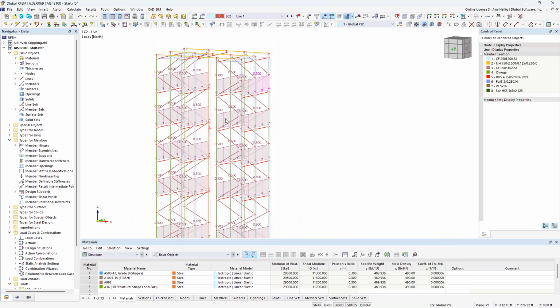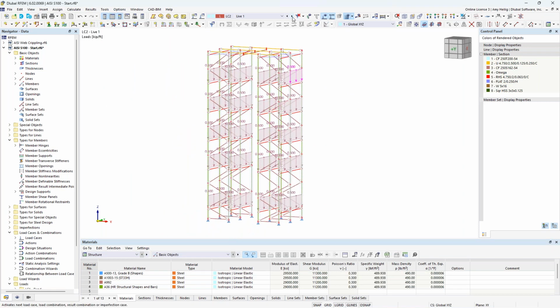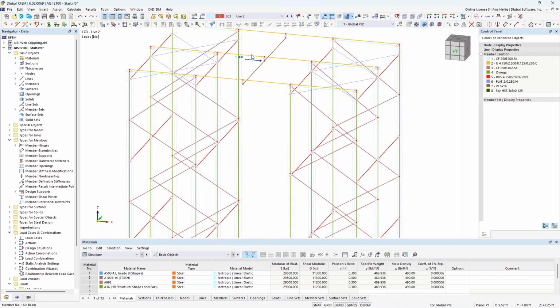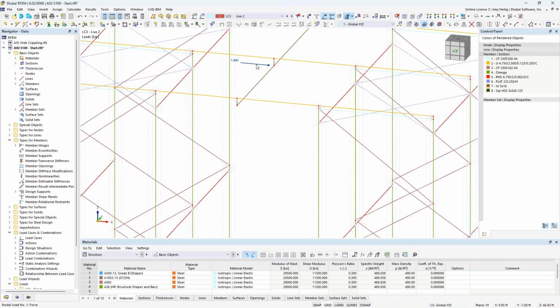So in addition to this first live load, we also have this second live load, and this is also a very simple application with a single nodal load applied up here to our center beam. So this load is just essentially introducing those horizontal forces to the entire racking structure. That nodal load can also be applied up here in our toolbar.